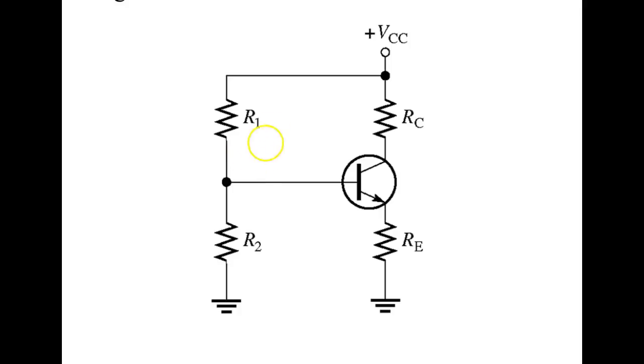So let's say we clamp this right here at 3 volts. Then right here I would have 2.3 volts. Well, what happens if collector current tries to go up? This voltage drop right here would try to go up, but it can't because the base is clamped at 3 volts. So this resistor cannot change its voltage drop. If collector current tried to go up, it can't, because it would try to make the base voltage go down, but the base voltage can't go down, right? Because it's clamped at what? This guy right here, it'll operate all over the place.